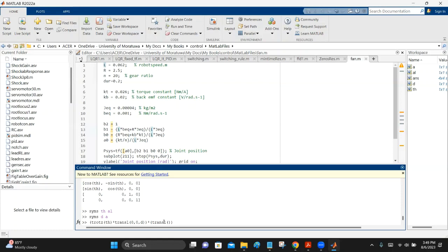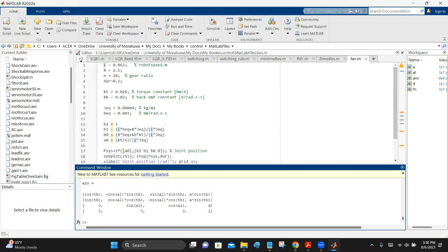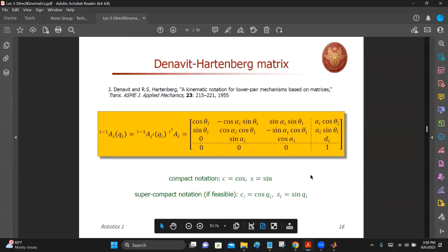This time it is along the x-axis, so it is a, 0, 0, times then the rotation, last one, t rot x by alpha, al. Now this is the answer. This is the homogeneous transformation matrix between frame i minus 1 and frame i. Over here you can see the same thing.